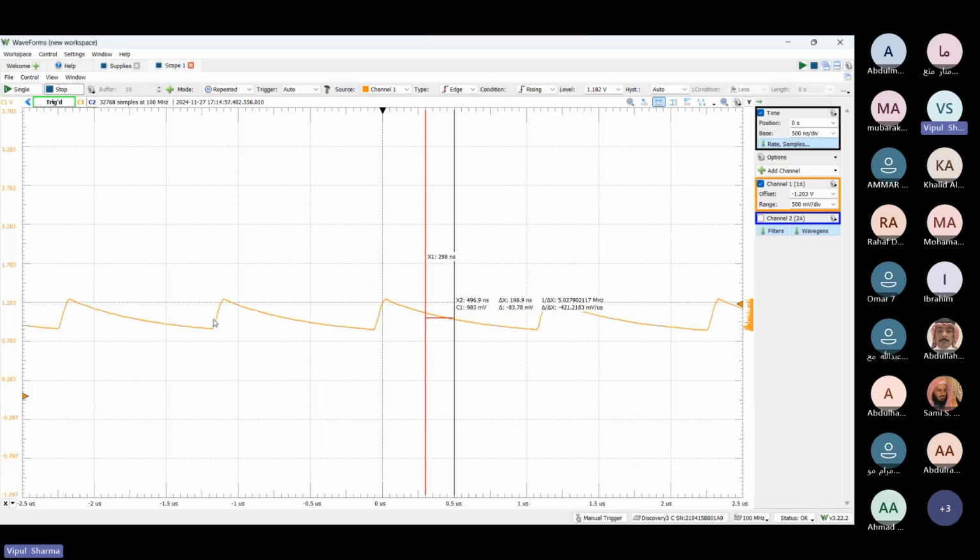So if this kind of a voltage is going to some operational amplifier or some LDO circuit, even if the supply voltage is varying from 5 volt to 4 volt, the performance or specs of that circuit won't deviate much from the expected value. So this is a requirement that a Bandgap reference circuit needs to fulfill for the biasing of analog circuits.